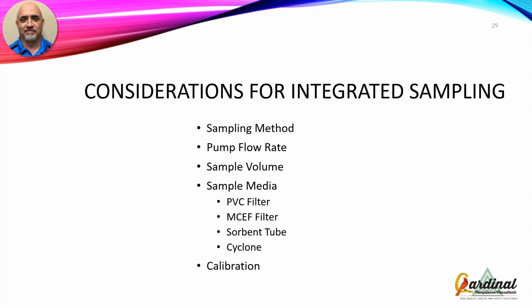Well, the reason for this, we do more asbestos sampling than any other type of sampling in industrial, things like that. You're constant, because there's some regulations that mandate it, right? And asbestos sampling is done at 2 liters per minute. But that's not always the case. Some NIOSH methods or OSHA methods, which is NIOSH, National Institute for Occupational Safety and Health, has a book called the Analytical Methods manual,